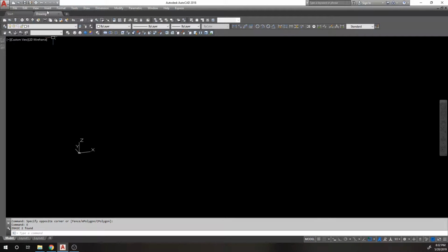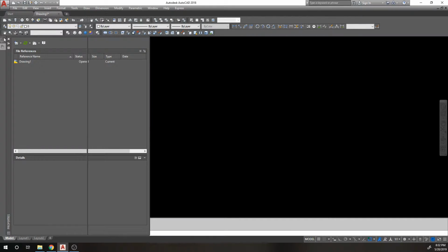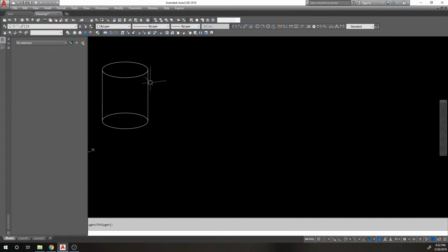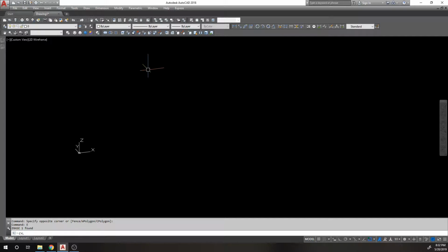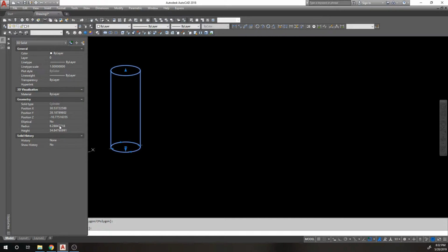But if you want to do more than that, you can do things like, so we know how we did the circle and we extruded it into a cylinder, right? Again, grip in the center. All we have is control over the height. Okay, but if we use a cylinder command by CYL or cylinder, we now can drag in both directions, and we also have grips at the bottom which allow us to change in the properties the radius and the height, not just the height.